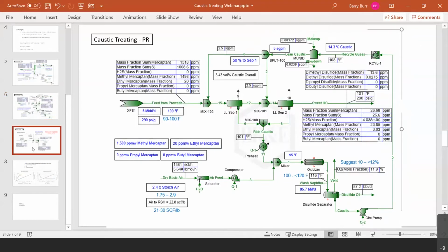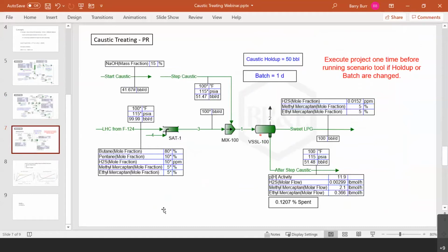And then we have a considerably different type of simulation that we're going to look at, and this is a case where upstream of the Mirox units, the examples of which we've just seen, we have a vessel whose purpose is to remove any remaining H2S from the incoming stream, because, as I showed in the first slide, any H2S that happens to get into the regenerative mercaptan removal process is going to occupy caustic and spend it, and eventually you'll be extracting mercaptans with a caustic solution that is spent with H2S and will be no longer of any use for the mercaptan extraction.